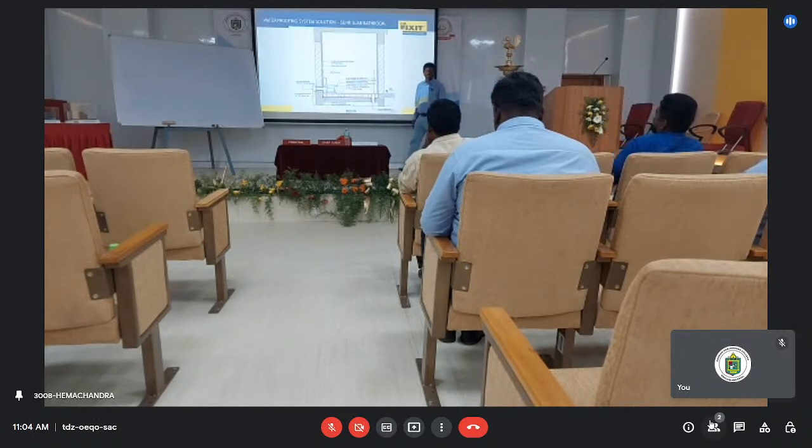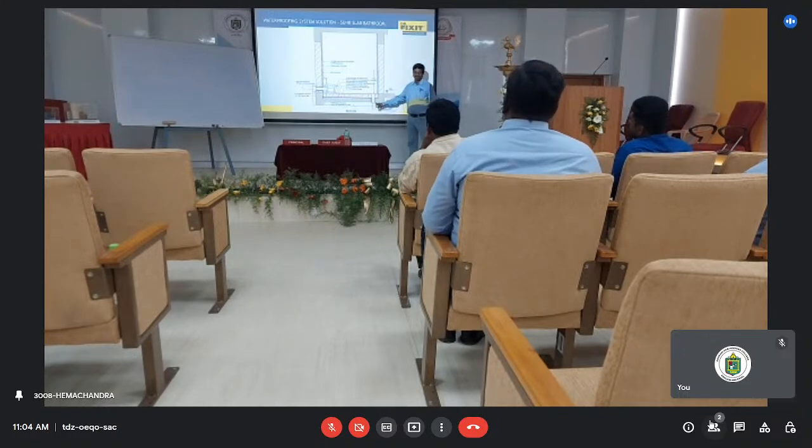So this is a typical cross section of the toilet waterproofing. First there will be wall packing, here wall packing, and this is for the water heater and area. Then two-component cementitious waterproofing coating, horizontal and vertical, 1 meter, and from the top, 300 mm.